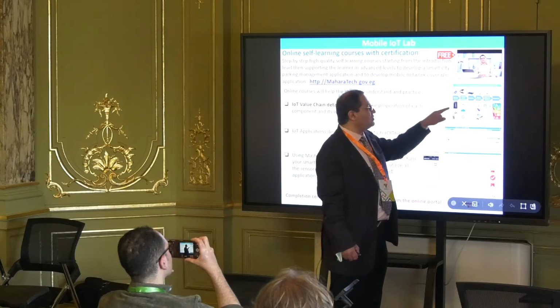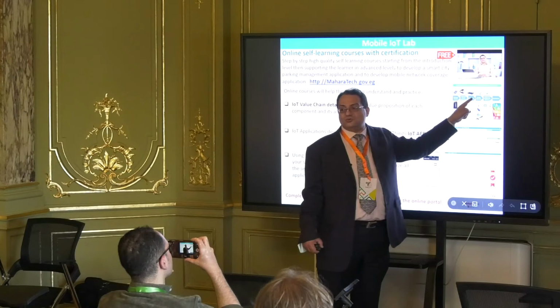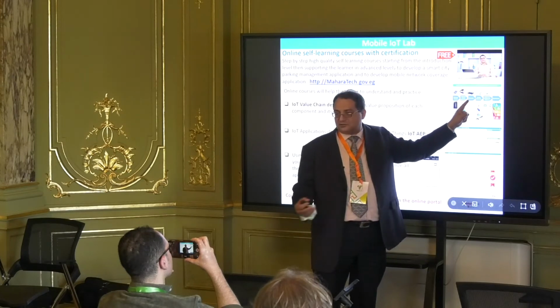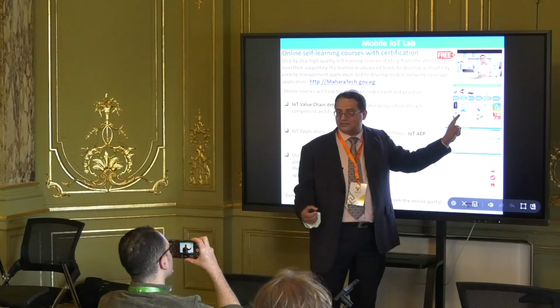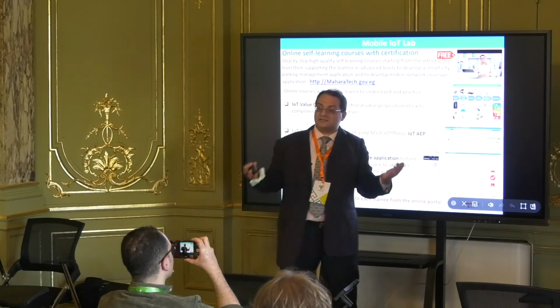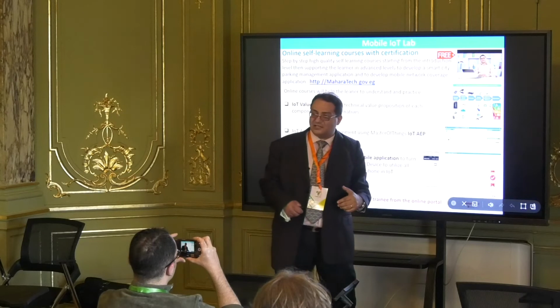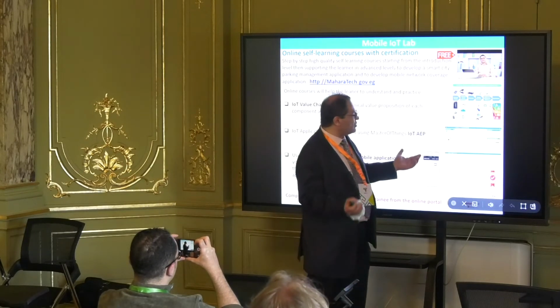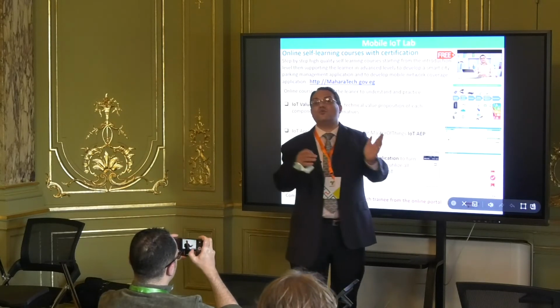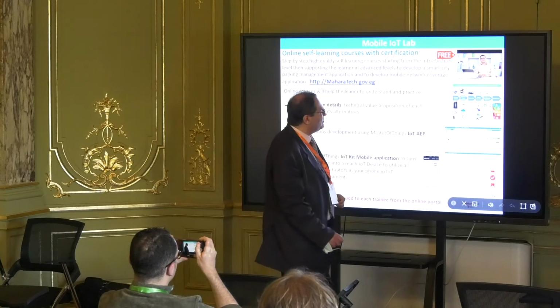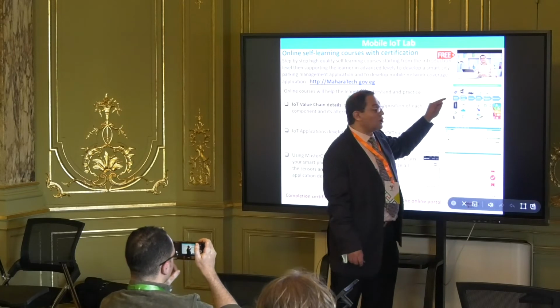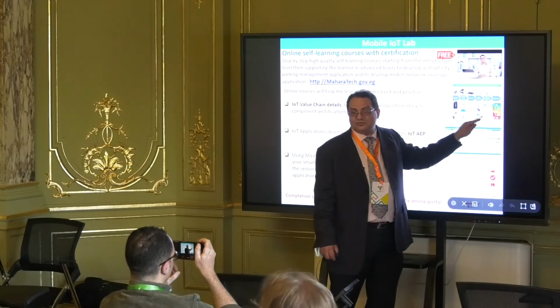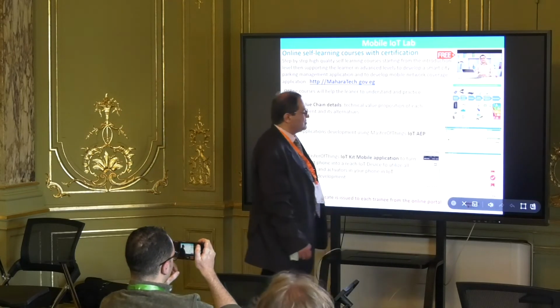So, for example, we talk about Sigfox, when to use Sigfox and when not to use Sigfox, when to use LoRaWAN and when LoRaWAN is not suitable. Bluetooth, which use cases it can be used for, the benefits of using Bluetooth Low Energy versus when not to go for Bluetooth Low Energy, and so on. So we take them from the concepts even to the details of the wireless technologies.